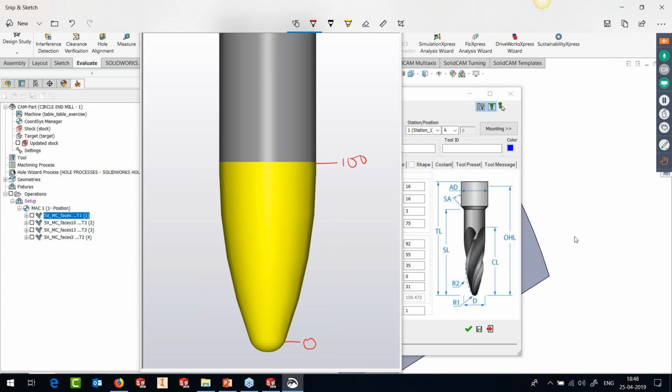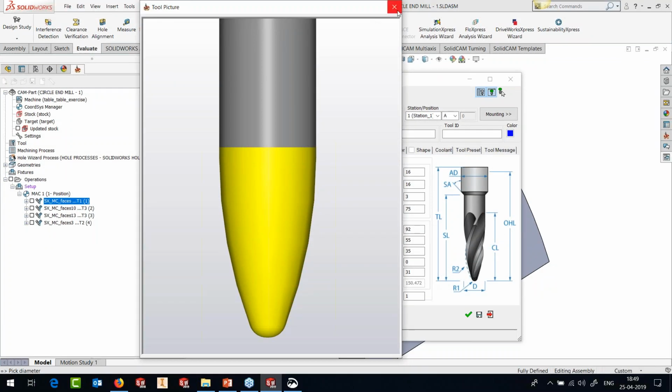My first contact point on the tool is going to be here at 50%. This is the point where it will generate the contact point, and it will start distributing this contact point till it reaches 10%. It will start putting depth cuts, and the tilt angle will be determined by where the contact point is on the tool between 50% and 10%. So this is what we are going to see here.